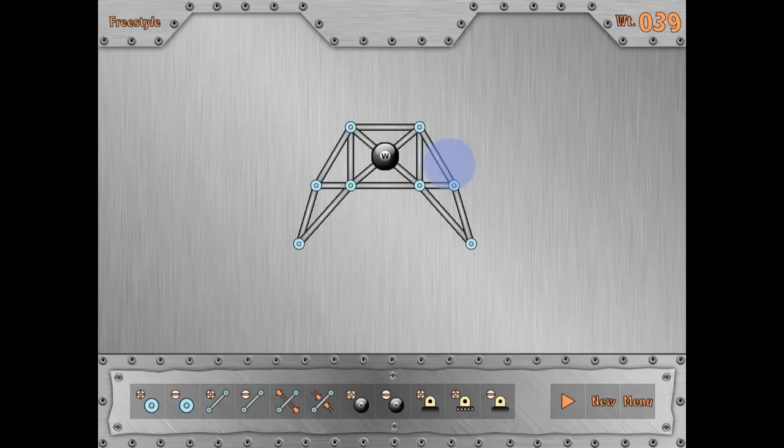There are two ways of addressing buckling problems on bars. One way is to make the bars shorter. We can do that by redesigning the geometry of the structure. The other approach involves increasing the moment of inertia of the bars. In practical terms, this means making the bars wider.